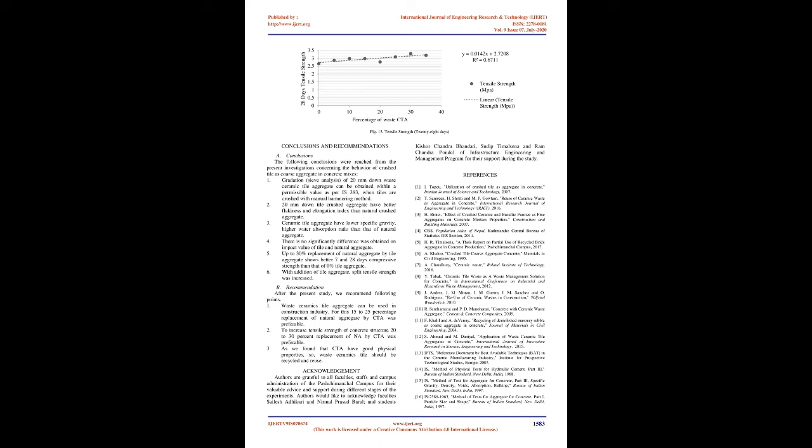The density of hardened concrete also depends on workmanship during concrete casting. Fineness of cement, grading of aggregate, and water-cement ratio are also governing factors for the density of hardened concrete. Concrete with 35% CTA had 5% less density than that of the 0% CTA mix.